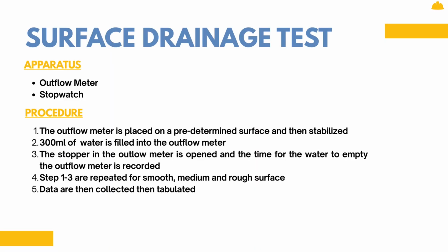On to the final test, the surface drainage test. The apparatus needed are an outflow meter and a stopwatch. Next, the procedures. First, place the outflow meter firmly on the selected test surface and ensure it's stable.